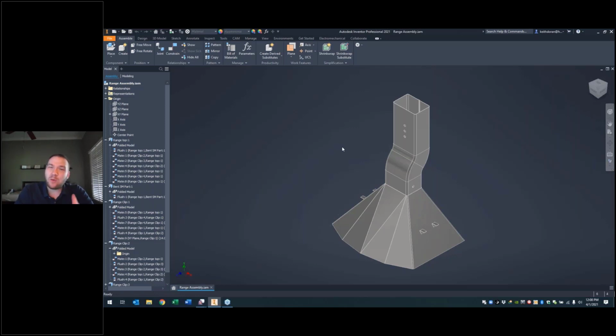So the first thing that I want to go over before I really get into that nesting space is I've got to make sure that the nesting template file has the information within it. This is a key step of the process to making sure that, when I take this data set and send it off to that nesting environment, it knows what materials I have access to, it knows what stock sizes I work with, and it also makes sure that I don't get any weird behavioral issues when I do that transfer.